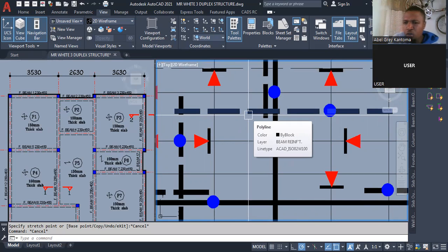That's the top distribution bar. What's the significance of that top distribution bar? What's the function? What's the job? If you leave your reinforcement return like this without putting anything, wouldn't it be flappy like this? It will be flapping.